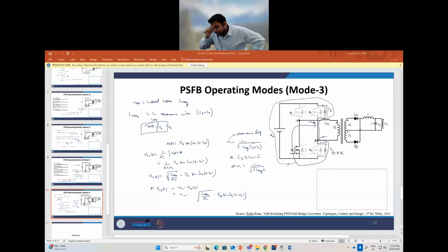Then second thing is that you can also do one simple thing. You can compensate that zero crossing point. How? There are techniques where you can softly do the transition of the totem pole bridge, the half bridge which is either clamped to VDC or 0, that means the slow switching bridge.